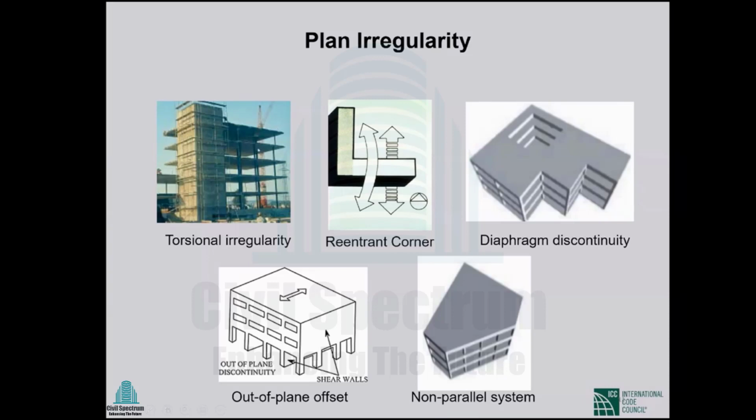So there will be torsional fractures in the columns. So this is very common in earthquakes, that due to torsional irregularity, buildings collapse. This is very important for the architects too. The architects all should be aware of this thing.